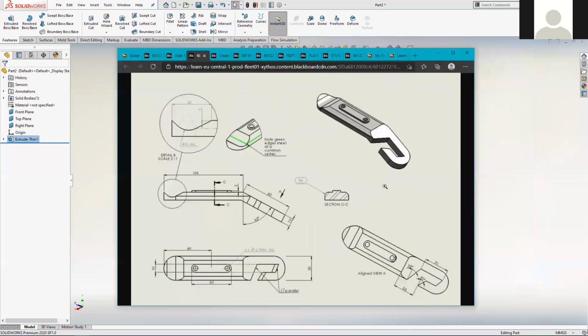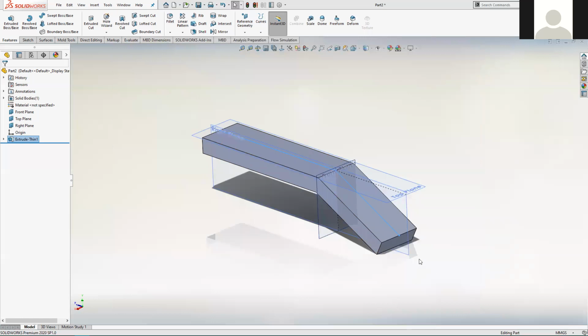But anyway, the feature that we're going to tackle first is these big round sections on either end of the part, which is just a fillet feature, but in this case, it's a special type of fillet. It's a fillet that you can apply to 3 faces, and the fillet looks at the first face, the second face, and the third face, and it deletes that middle face. That second face gets deleted and replaced with a radius that spans the other 2 faces. But all of that will become clear when we actually activate it here.